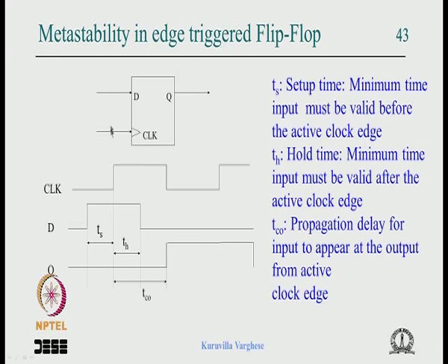And if you analyze a master slave flip flop from which this edge triggered flip flop is constructed, for a positive edge triggered flip flop, during the negative clock period the master is in transparent mode.